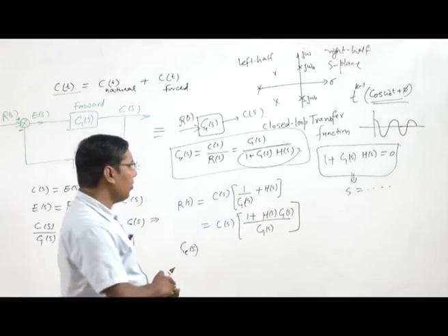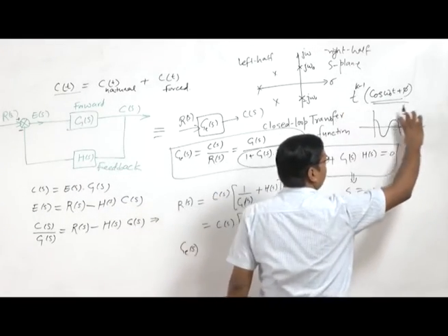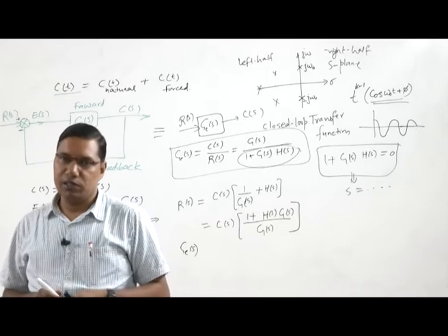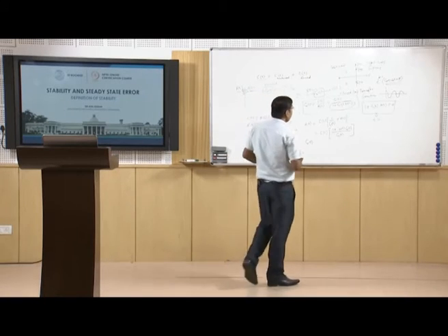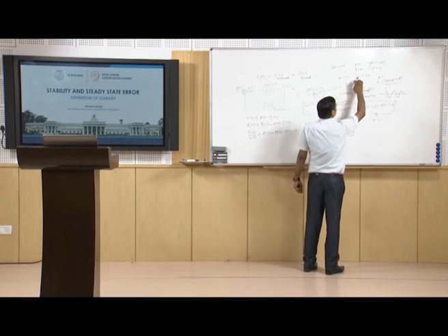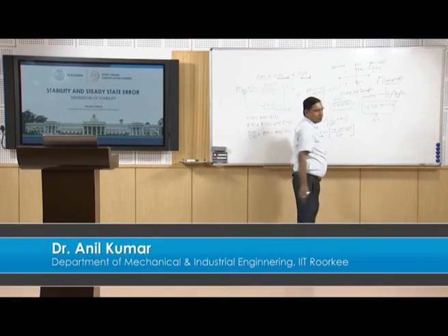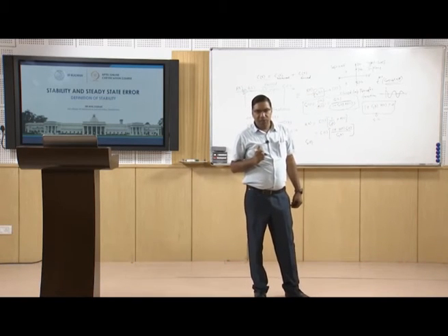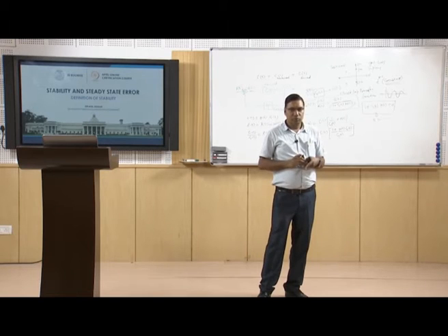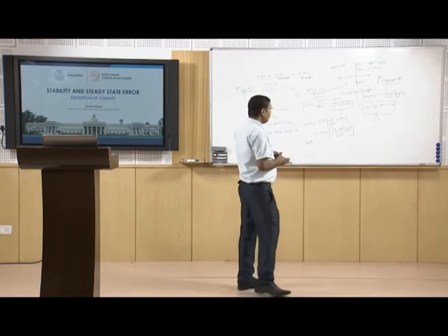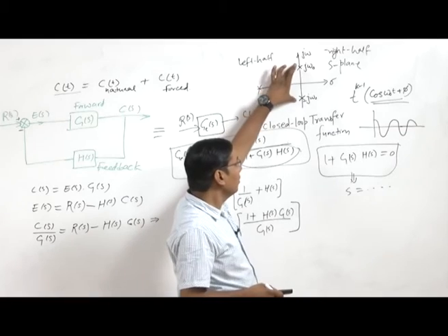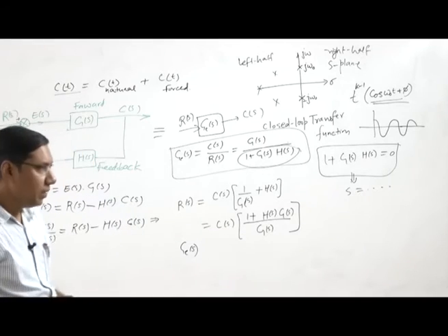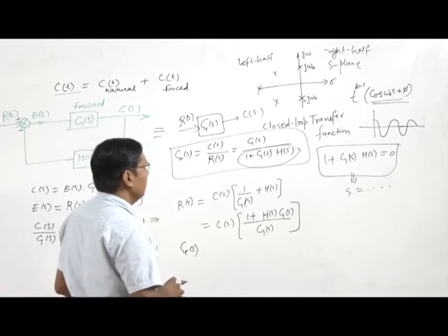When t increases, this will increase, and the system will be unstable in this case. Therefore, if there is one pole pair here, the system is marginally stable. However, if there are poles with multiplicity greater than 1, then this system will be unstable.